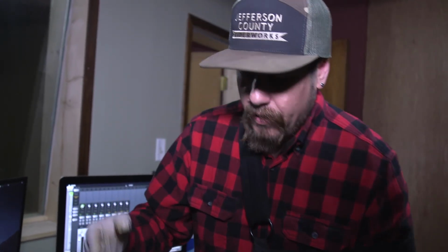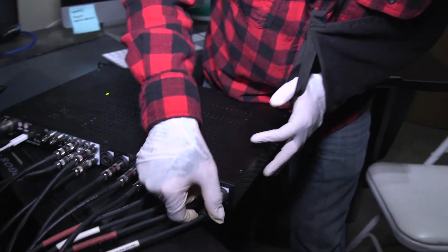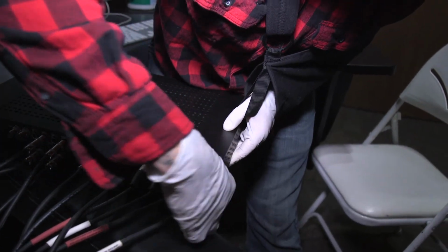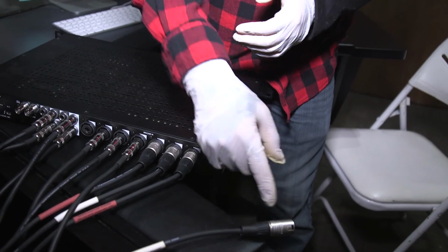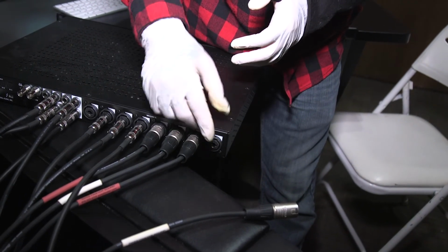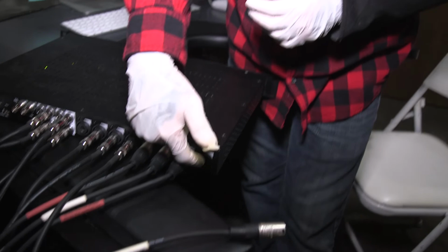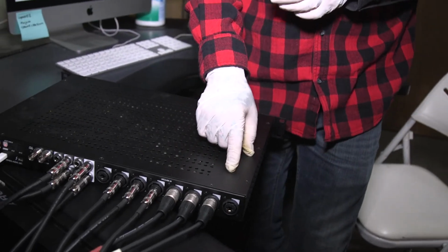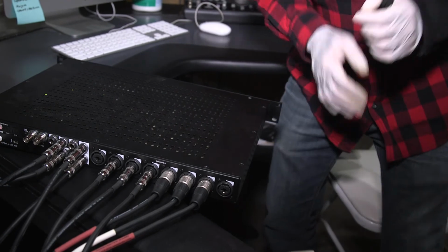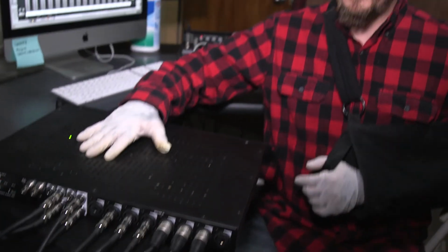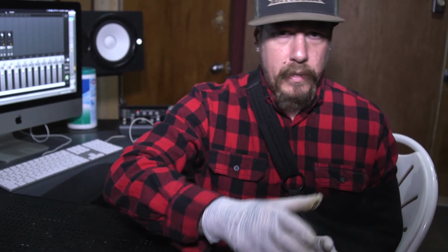But sometimes people like to come in here and unplug input 1 just by reaching behind there. If you do this, make sure that your phantom power is not turned on. Make sure when you're unplugging cables that the phantom power is off. And then they like to hook their own XLR cable up to this, and set the microphone in this room. Now, you're not going to be able to pull this out, but you can reach around and pull out input 1, connect a new XLR cable, and set up a microphone right here in the control room, and you could engineer yourself.